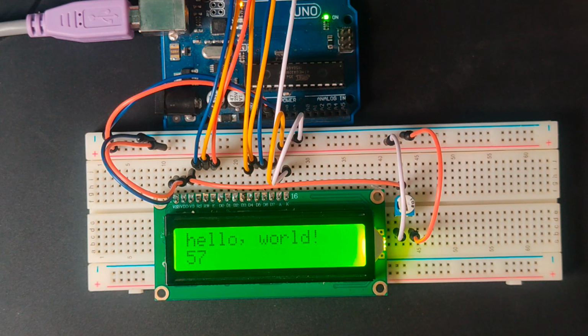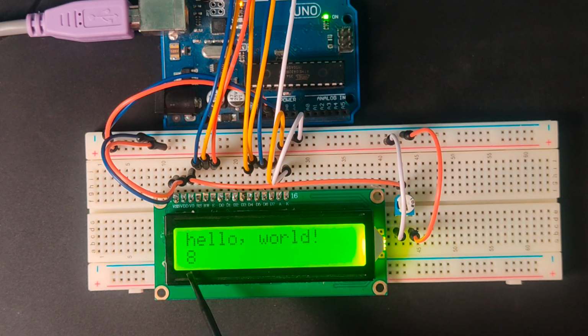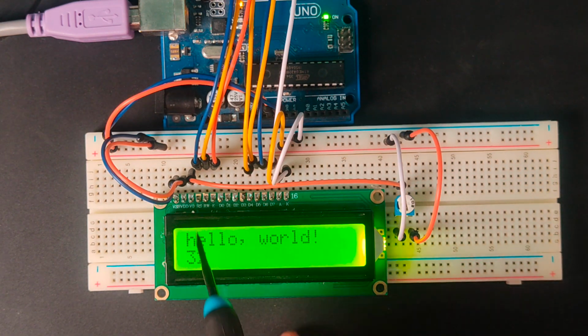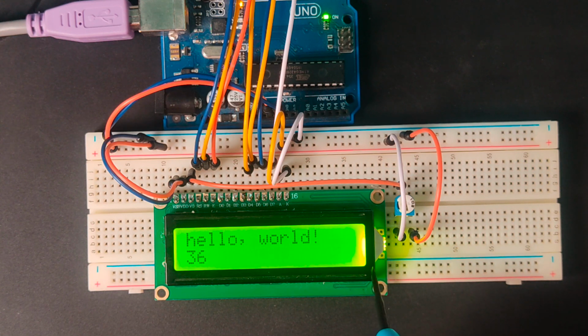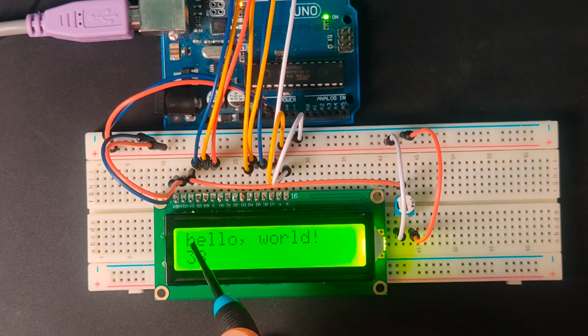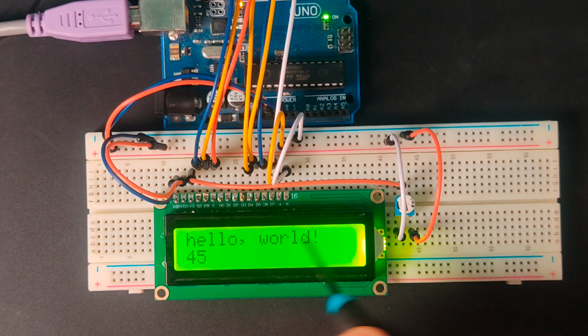So let us press reset in here and see what happens. It restarts from 0, and then it will be printing again. So that is hello world over there. These numbers 7, 8, 9, these millis, are as we have said. So we are at column 0 and row number 1. The letter H in there is in 0, 0. Letter E is in 1, 0. Letter L is in 2, 0, and so on.